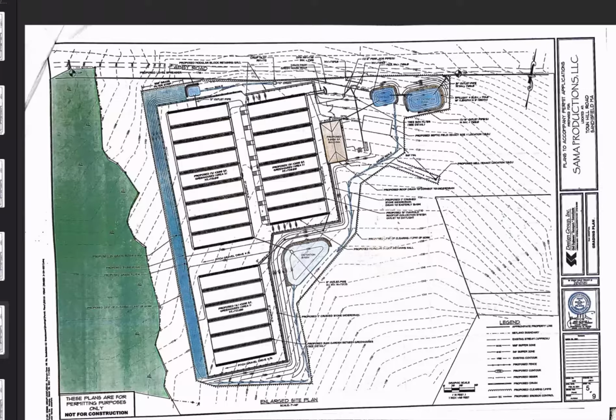So that's the plan. This will be a gravel yard around the greenhouse structures, and that will provide adequate parking. Additionally, location: parking can be located no closer than 100 feet to the road, so I carefully located my building and my row of parking 100 feet away from the property line.